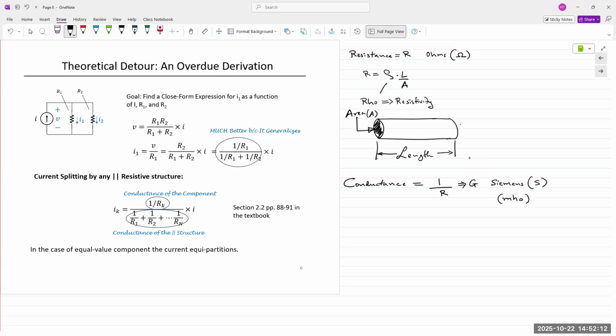A practical look at this is in long distance transmission lines. We talk about circuits as ideal conductors, right? On paper, when you're performing analysis, we're talking about wires. Wires, very low resistance, 0.2, 0.3 ohms, definitely less than 1 ohm. But this is where it comes from, rho L over A. You can take the best conductor on the planet, which has a few milliohms as resistance. But think about long distance transmission lines that go over hundreds of miles.